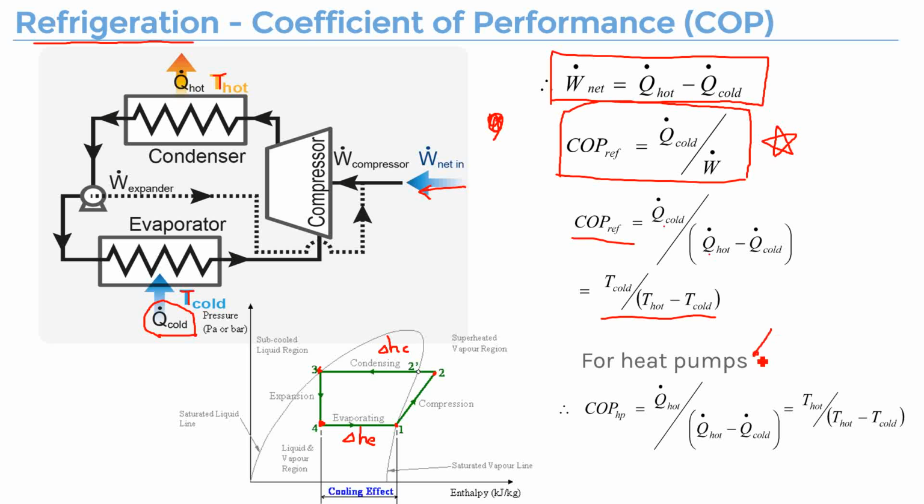Another concept is heat pumps. But as we said, for heat pumps, you just reverse the direction, or you just swap these two places. For example, in winter, the indoor environment is actually the condenser side, and the outdoor environment would be the evaporator side. So it might take time for you to fully understand all those. But now we are just introducing these cycles for you. Do you have any questions on this part?